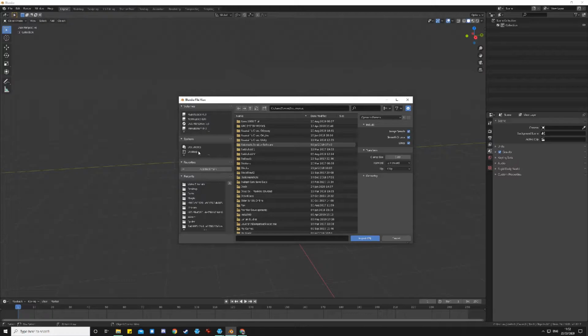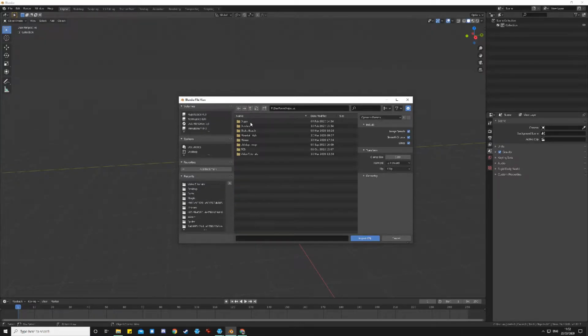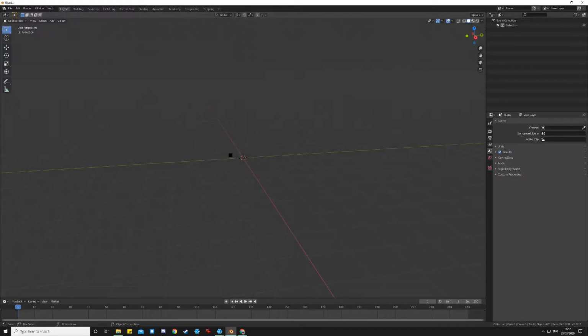So within Blender, if we just go to mouse, I just got to find it, there you are, mouse folder, MeshroomCache, texturing, in the folder with the long name, and all I need to do is click on this one, which is the obj. It'll drag in the textures, it will drag in the MTL and all that stuff that we will need at some point, but you just need to do it from here initially. So we import the OBJ. That square means it's loading, and it's just spending some time working out where it all is.